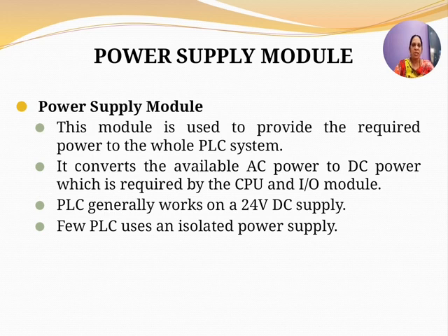What does this power supply module do? It converts the available AC power into DC power, which is required by the CPU and the I/O modules. The CPU and the I/O modules work on a DC supply. Hence, you need to convert the AC power into DC power.